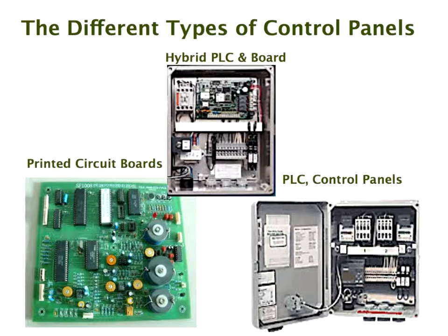But if you go into a separate pump with a separate pump tank and run it from the same controller, there's absolutely no problem whatsoever if it's set up correctly. But you can't do it with one pump, which I think might be the question Mary Clark's really asking. If it's one pump, I don't like it. If it's two pumps and the controller is set up to do the same functions, why not? There's no reason not to. And in large systems, this very frequently is done with one very large custom-built control panel.